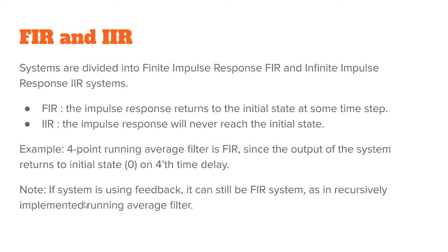Infinite means that it never ends. It's like any analog filter, RC filter. It decays but never goes exactly to zero. So it goes very close but never exactly zero. So, for example, that 4-point running average filter is FIR because after the 4th time delay, the signal is zero on the output.